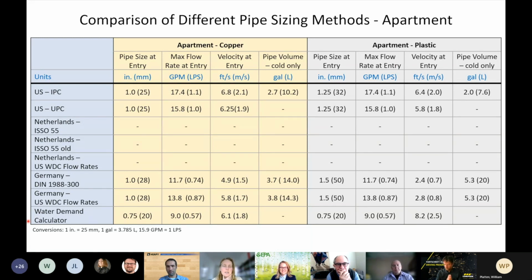Thank you. Well, one to add to how bad is it if you oversize pipes, I think, well, we've done some temperature modeling. We also saw the water in the pipes getting warmer and cooler and warmer and cooler depending on flowing or stagnation, and the temperature could be different in the risers or in the horizontal sides, and you just don't know what's happening at all, and that could affect all sorts of biofilm related issues, even with or without chlorine residual.